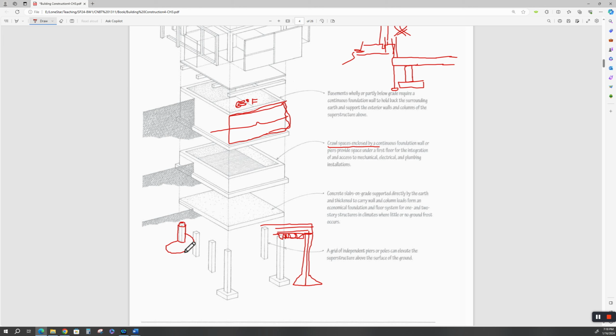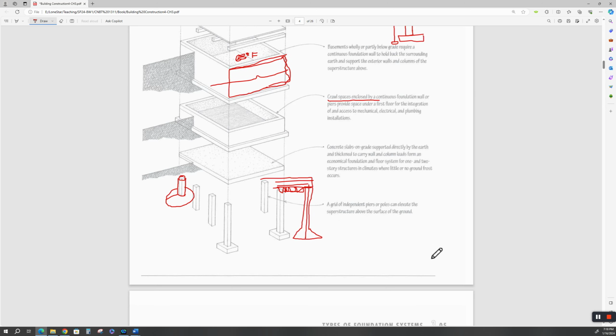Pretty poor drawing, but that's what happens, and that has to go all the way around. There we go. All right. Okay. So that's a bell bottom pier. You may have seen some of the drilling trucks driving around that have that. The actual bell section looks like a big giant can. They hook to the drill stem. The drill stem is an auger. Then they take the auger bit off, and then they hook the can on it with the drive shaft for the drill.